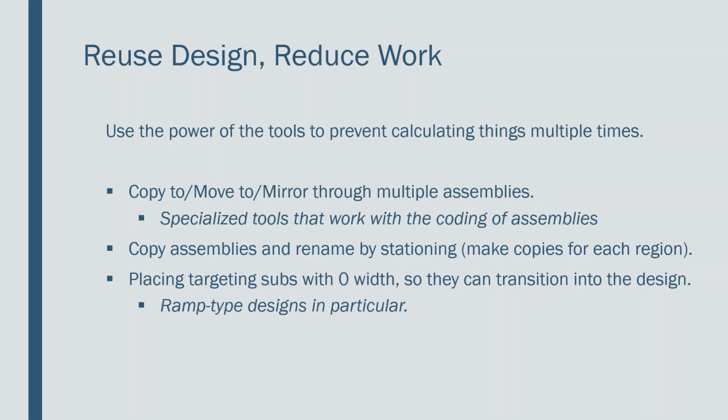Copy assemblies, now, and again, I have to make a distinction here. You can copy assemblies with the AutoCAD copy. The subassemblies you can't, but the assemblies you can. And one of the benefits is if you have the same assembly or generally the same assembly in several different regions, again, copy the whole assembly and then go in and make the tweak changes that you need to after you've got them in place, if there's any differences at all.